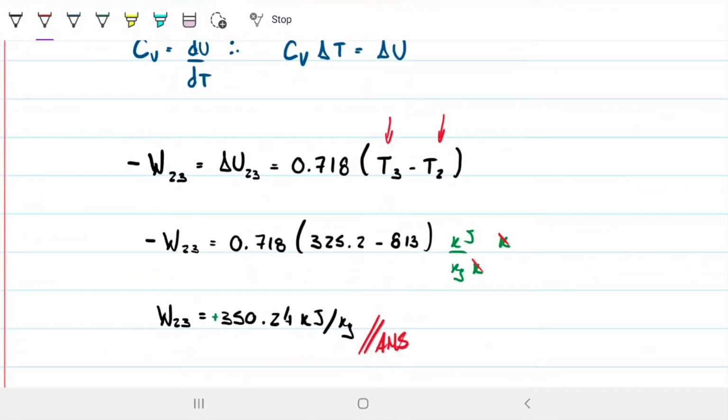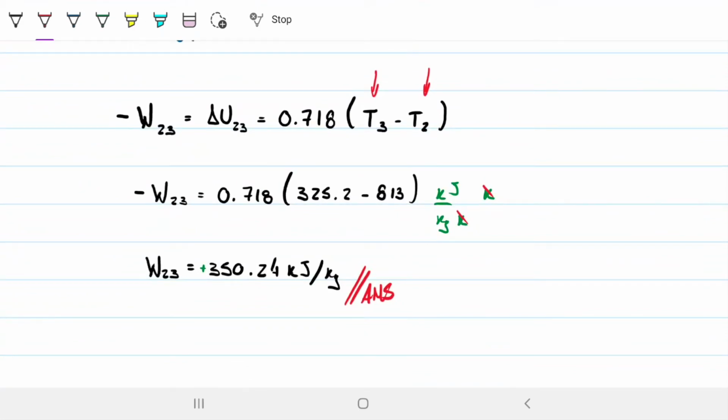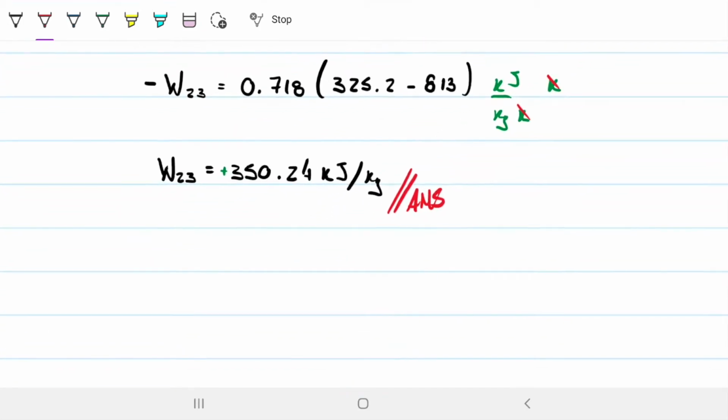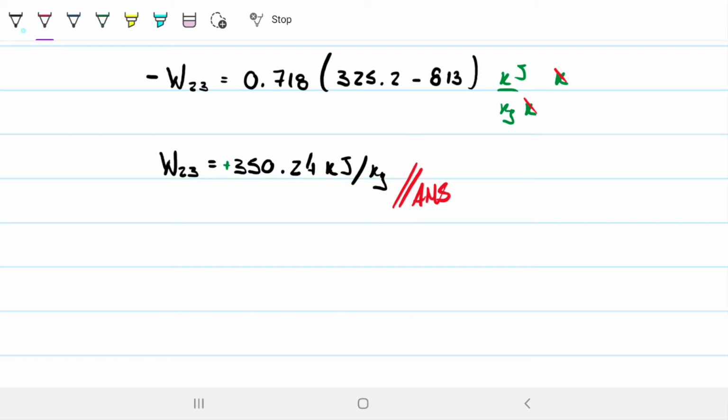Okay, and then because this is a Carnot cycle, we know that on the other side it has to be exactly the same, or else it's not going to be the ideal situation, right? So we're going to do this again, obviously for 4 to 1, but we need to find exactly the opposite, the same amount of energy, but because of the compression, something that's going to be absorbed, right? So it has to be 350 on the other side. But that's quite obvious, right?